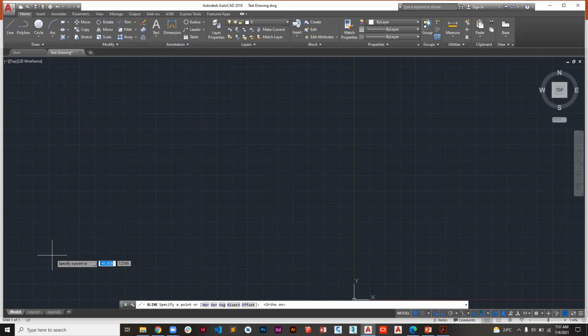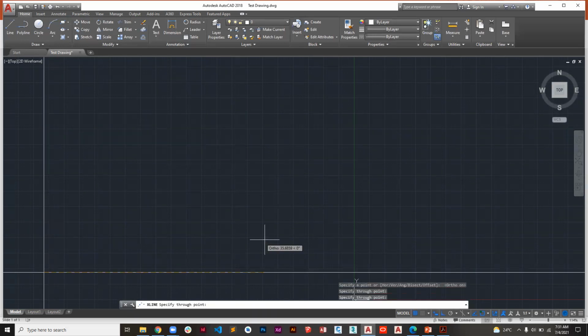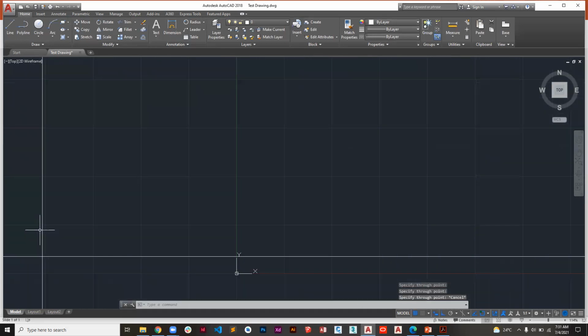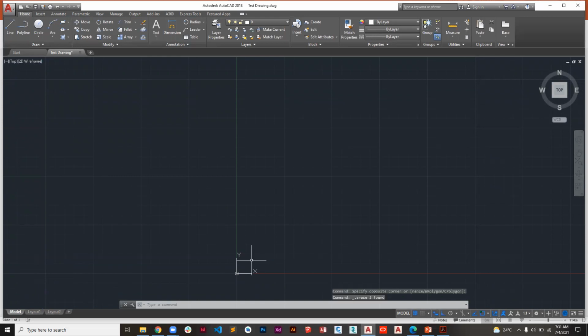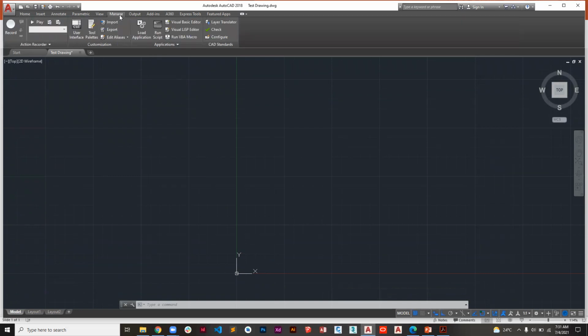Like you always use the construction line, then from these lines you can start offsetting, then you trim. So you can record this action of putting these two lines so that the next time you come, you just play that action and they are drawn. Okay. Yeah, so that's when you can use the action recorder. So that I don't have to draw them again. Yeah, you don't have to draw them again. So it's like macros in Excel, if you ever use them.